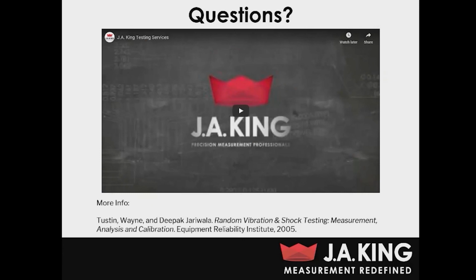Do you guys do any of your own fixture designs? Yes. So if you guys have your own fixture and you'd like us to use that, we can do that for you. We can even help you validate that fixture too. If you want to send it to us, we can do a sine sweep and make sure it'll work for the test. Or if you'd like us to just completely handle the fixture design ourselves, we can do that too. You can feel free to send us over CAD models or drawings or even the part itself. And then we can go ahead and design the fixture, and we'll perform all the fixture validation that's necessary before testing as well.